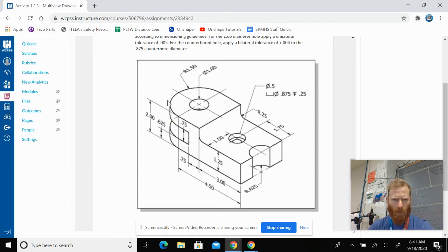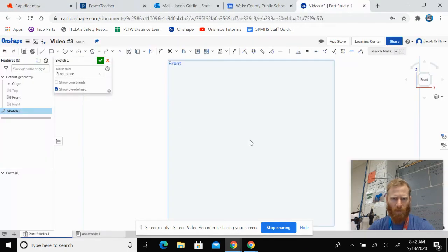While I'm doing that, I can go ahead and model what I call the alligator mouth. I see that the bottom lip is 0.625 inches thick, or inches tall. And then the gap in the middle is 0.75. If I do 2 minus 0.625 minus 0.75, I can find that the top lip is also 0.625 inches. So let's get started from there.